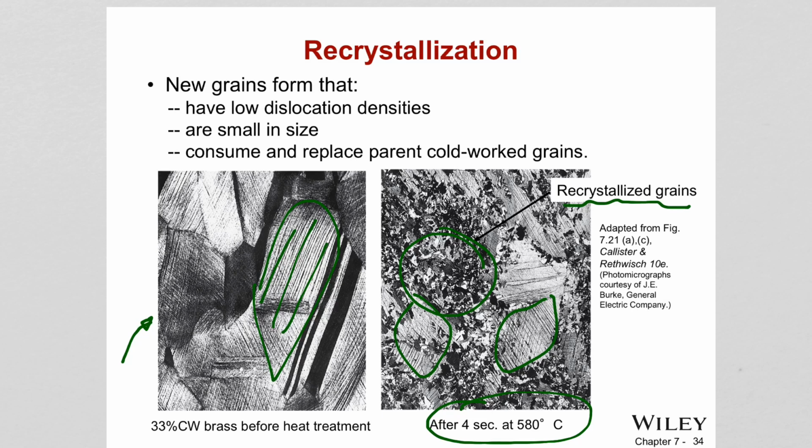information. And then dislocation density is therefore decreasing because the dislocations were already used in the forming of new and small grain boundaries. So basically you need to know that in recrystallization, the number of dislocations is decreasing, the grains are becoming new and small in size, and this makes the material more ductile and therefore easy to deform.